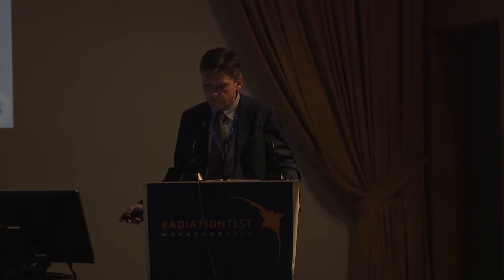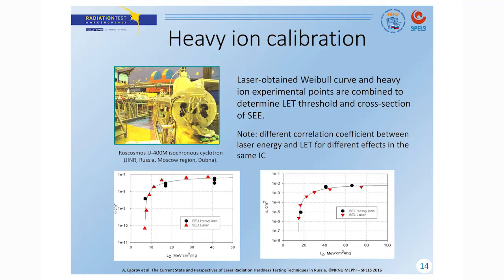And to estimate the laser energy losses and to determine the correlation between laser pulse energy and LET, in this case we use joint use of laser and heavy ion tests. So here you can see example results of this technique. We have enough experimental points on this curve to make a correlation between ion experiments and lasers.